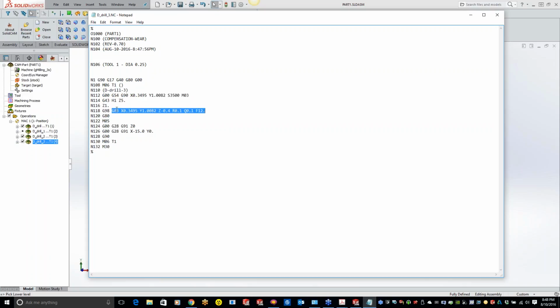So yeah. Okay, so what the G code is actually doing here is we're telling the machine we're going into a pecking cycle using a G83. We're going to the location that we specified off of the origin point.